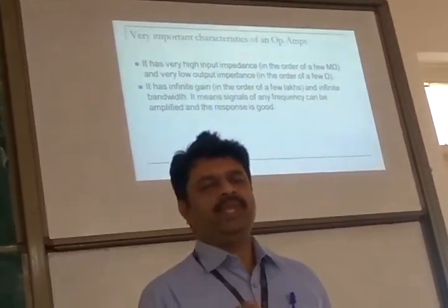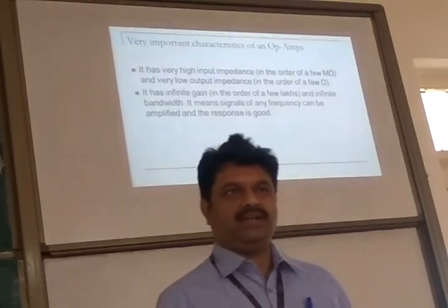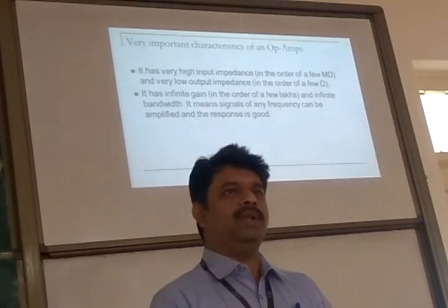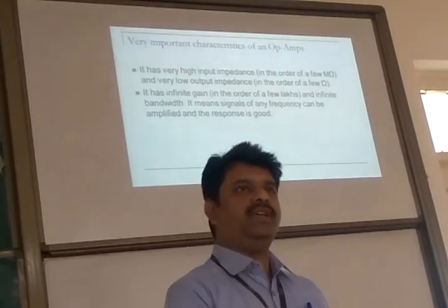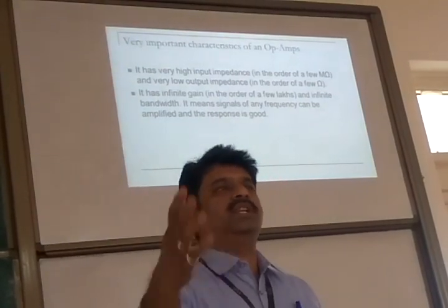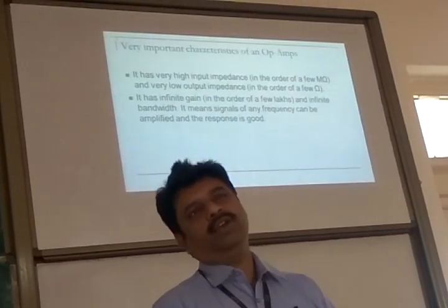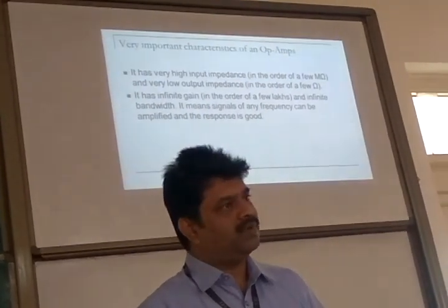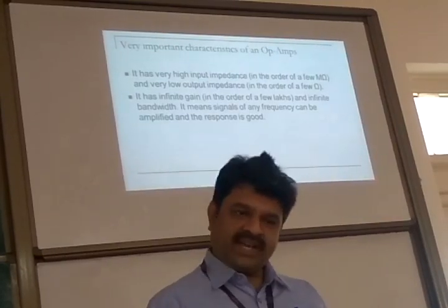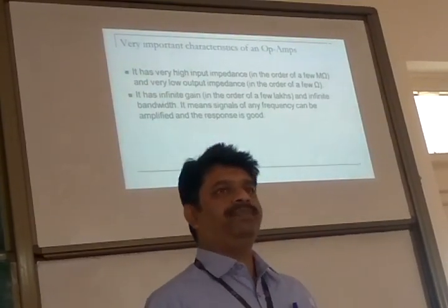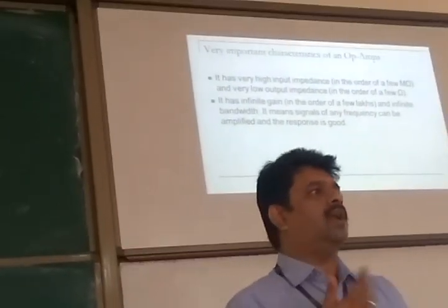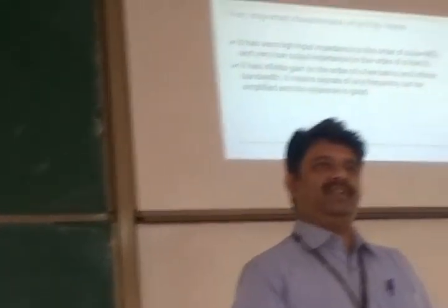Those who want to test, take one normal amplifier, connect it to a thermocouple, and you will be able to see the effect if input impedance is less. You give the input signal, take the output signal, connect it to a CRO or a very good multimeter and see the output. Sometimes the output will be zero. The thermocouple will be working, the circuit will be working, everything is fine. That's because the small signal coming out of the sensor is already eaten away by the amplifier.